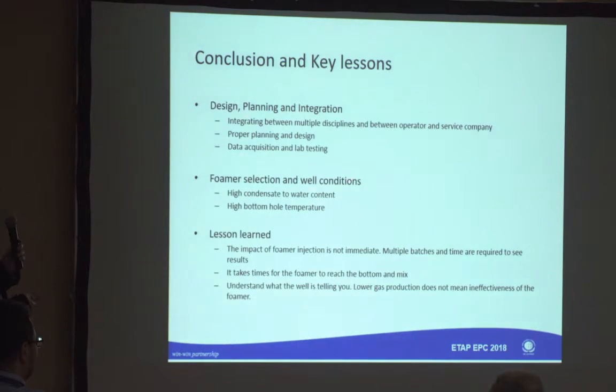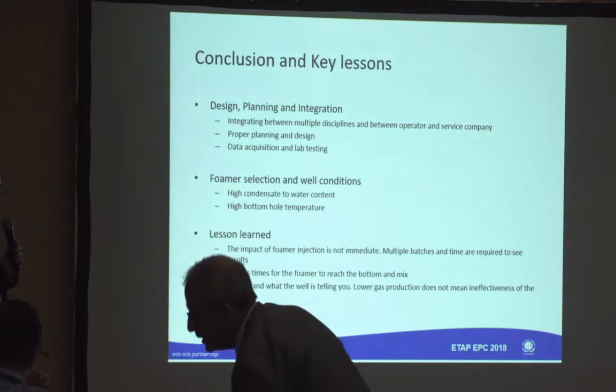The data acquisition and lab testing that we did, and also the fact that you have to have a way of really measuring the impact of the foamer on your well, so that you're not just looking at the gas rate, but looking at different other parameters to understand how your well is reacting to your foamer injection. Proper foamer selection as part of the lab testing, and one of the key lessons learned to take away, I think, from this presentation is that the impact of foamer is not immediate.